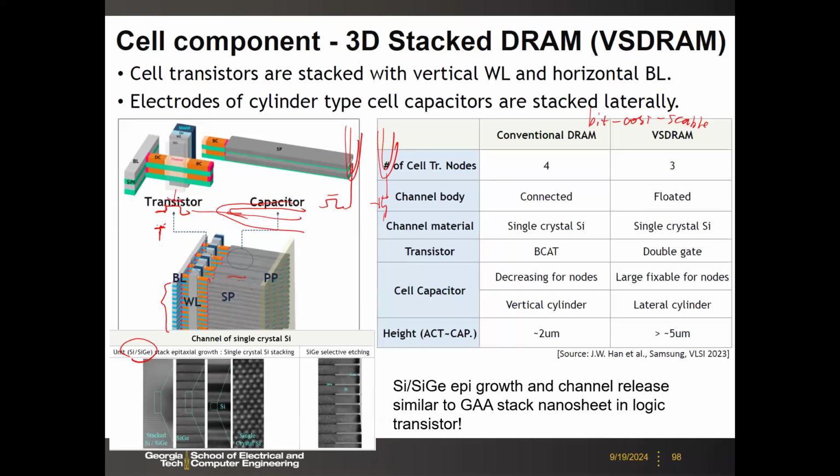It's not very attractive. So here the key is that you have to do the deposition of many layers, and after that, one lithography step to etch. Okay, it's multi-tier deposition, one litho, multi-layer etch. This is the key. Okay, so I will show you some more details in the next few slides, but from the architecture point of view, this is how it looks.